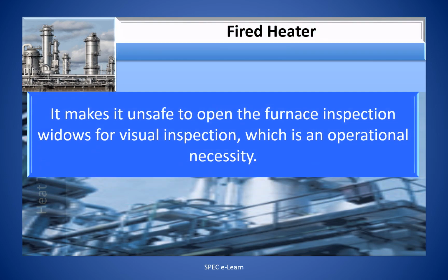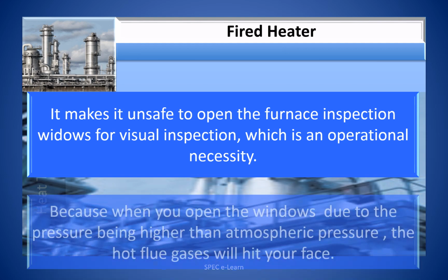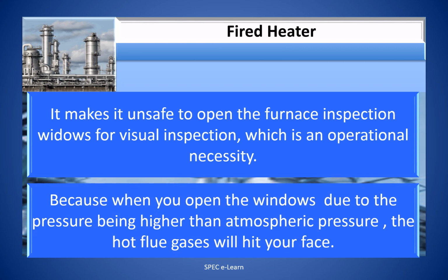It makes it unsafe to open the furnace inspection windows for visual inspection, which is an operational necessity. Because when you open the windows, due to the pressure being higher than atmospheric pressure, the hot flue gases will hit your face, as discussed earlier.